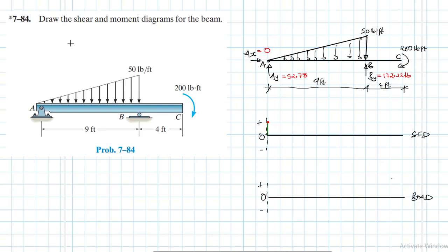We are not going to do the sectioning method where we section. Instead we're just going to use the differential equations that relate load, shear, and moment. We have dV/dx, which is equal to minus the distributed load, and dM/dx, which is just equal to the shear.